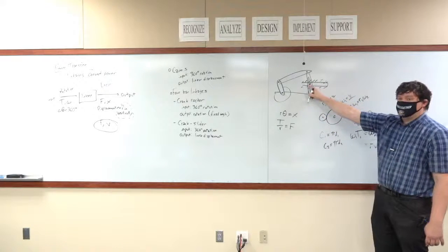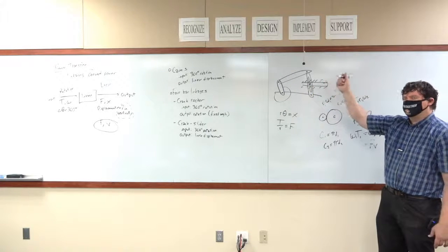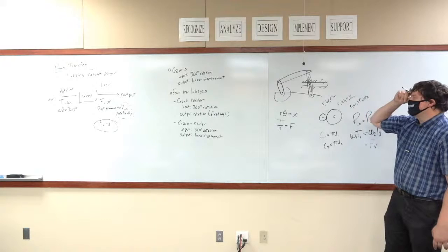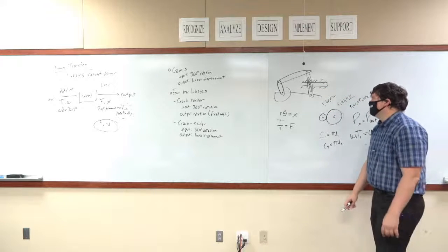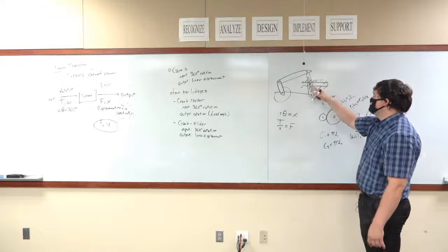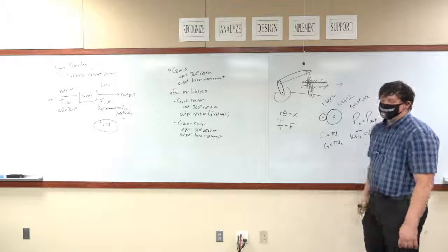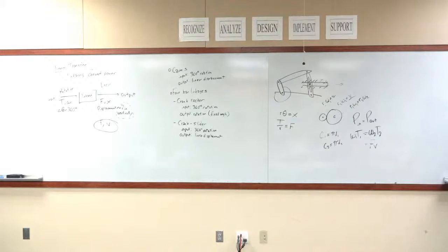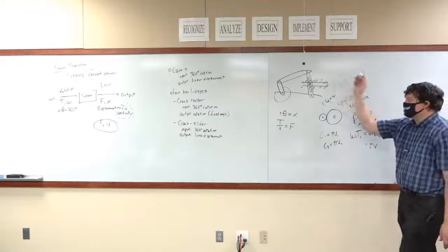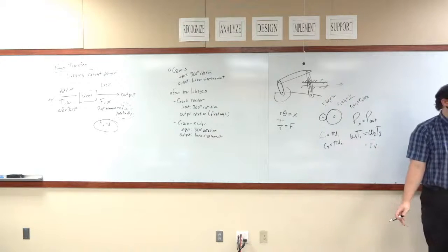Okay, and it's got a 1 degree of freedom joint right there, where it can rotate relative to your rocker. A 2 degree of freedom joint, because it can also move up and down. But it's constrained from moving this way. You will get a linear displacement out of that. That's all it takes. You can take an angular rotation and produce a linear translation by attaching it to another mechanism.